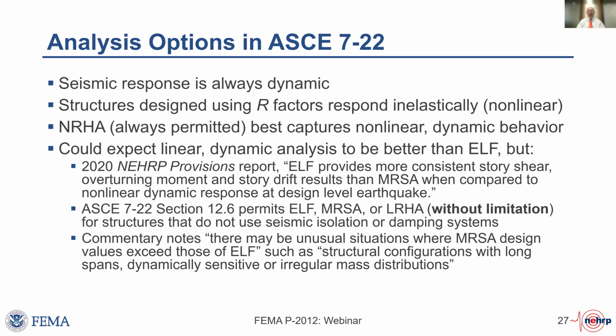So when you take the gold standard, let's say, of nonlinear response history analysis, with its story forces, overturning moments, and drifts, and compare it to modal response spectrum analysis and to the ELF envelope, the ELF results probably do a better job of capturing that nonlinear response.